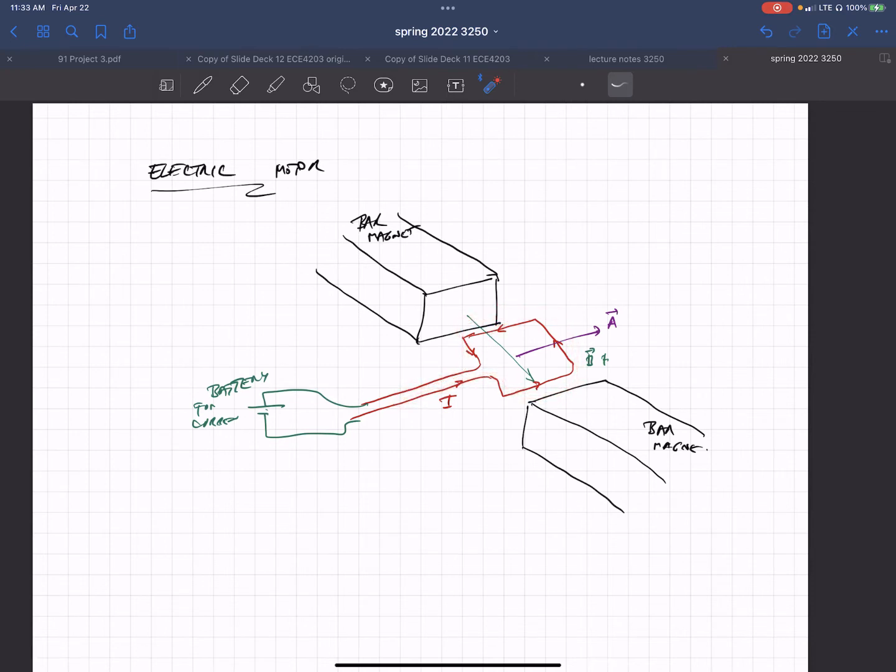And then it starts rotating that way, because every time the dipole is lined up and happy in its low energy state, you completely flip the direction of the current and you make it rotate again. You keep up that process and you get this rotating thing.